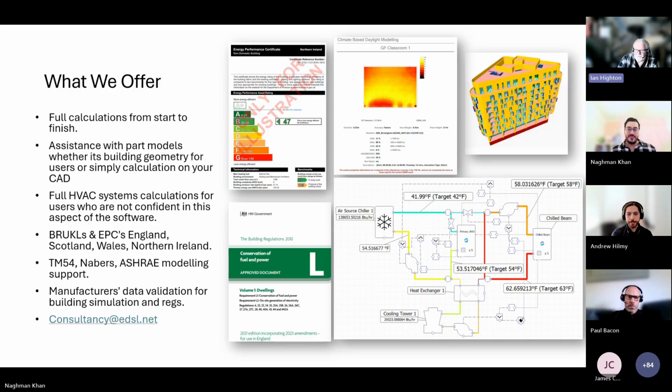The energy center feeds off the plant rooms, and the plant rooms feed off their airside systems. So you just have to chase the problem down. But where you spot it is, maybe you'd spot it in the airside schematic, maybe you'd spot it in the waterside schematic, but the energy center is probably a good place to start, just as a sort of sanity check.